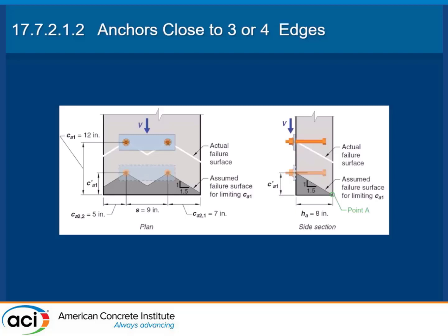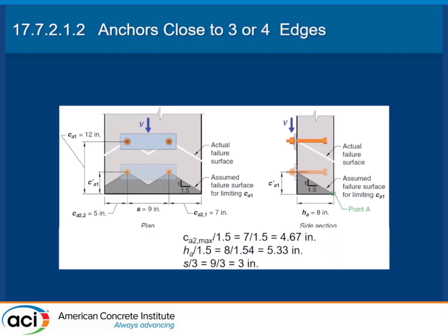Let's not think of a thin slab, let's think of a precast panel. Just because I move it back further doesn't mean I'm getting any more actual capacity. I actually have a fictitious, or a reality, distance to the edge that I would run my numbers with. And the code's pretty clear on how to run that too.